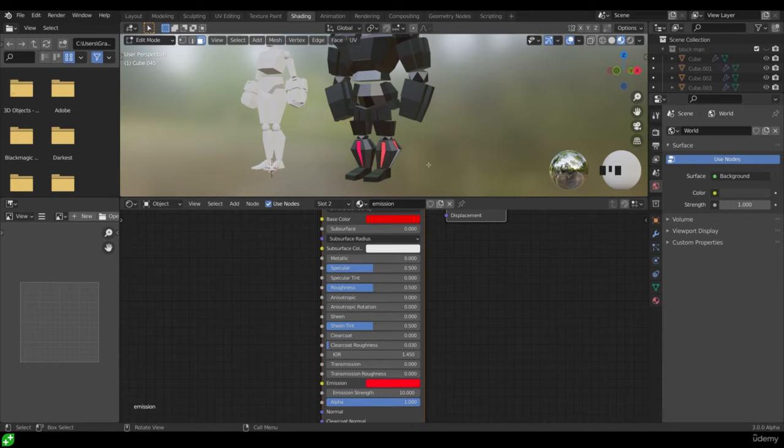and with one of your objects create a new material slot. In that slot create an emission material, and then go into edit mode and choose the faces of that object that you want to assign that emission material to. Pause the video and have a go at that.